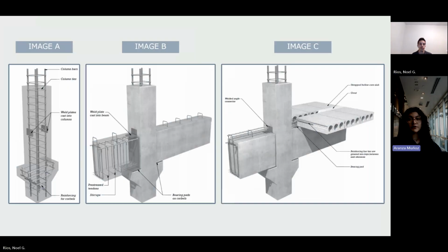Another example of uniting precast concrete members is represented here, where the beams in this system of framing rest on concrete corbels that are integrally cast with a column. The smooth top hollow core slabs are detailed for use without topping.